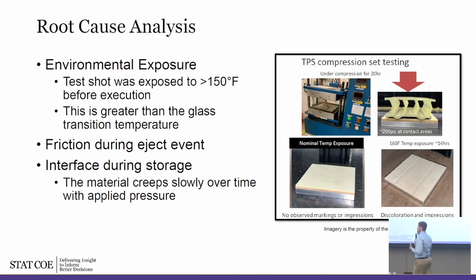Okay, were the striations there before? Were they caused by the flight test? They ended up settling on it was probably during storage, where there's the significant weight of the round pressing down on the pads, and the protective coating gives and deforms a little bit. It's known as creep, so it'll be a little thinner under the pad, a little thicker around it.